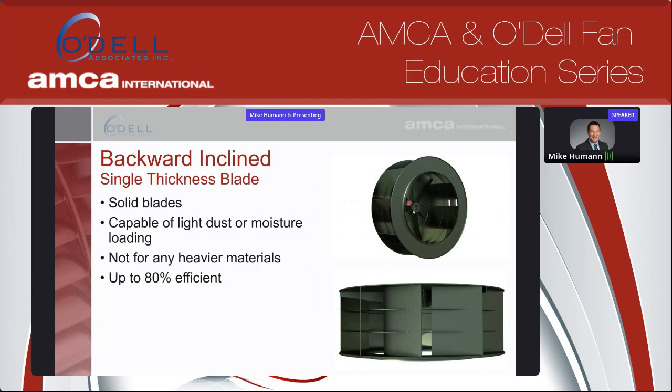And you can see a large inlet, and we talked about our large ID on the inlet side of the wheel, and talked about how much flow these handle versus pressure. And you can see they're much more efficient. You're up to 80%, and again, not for handling heavier materials.